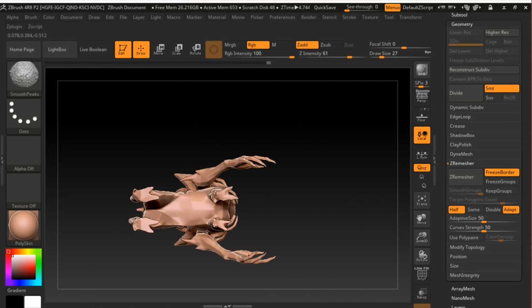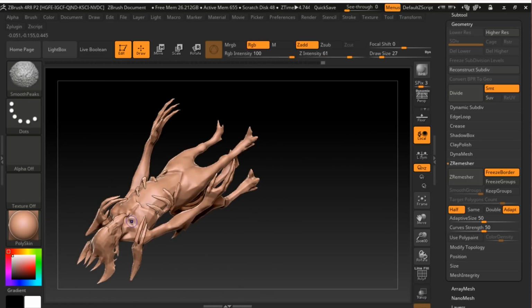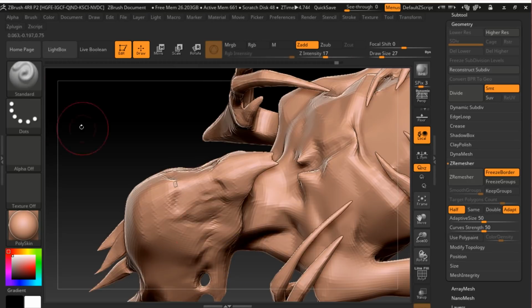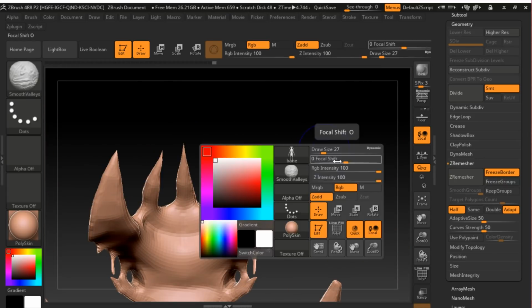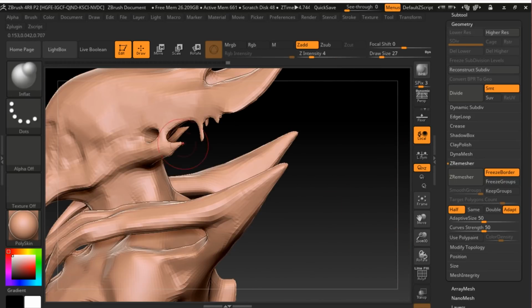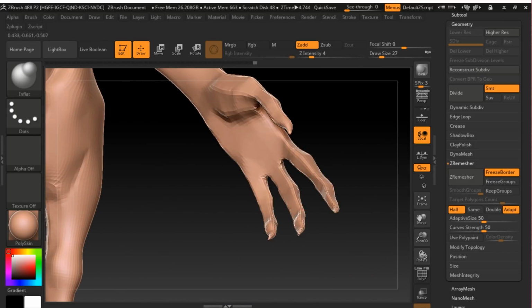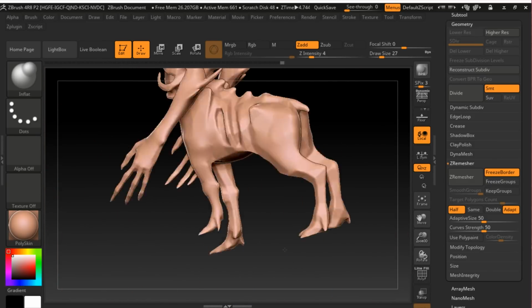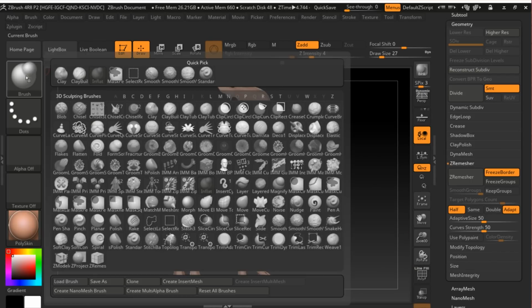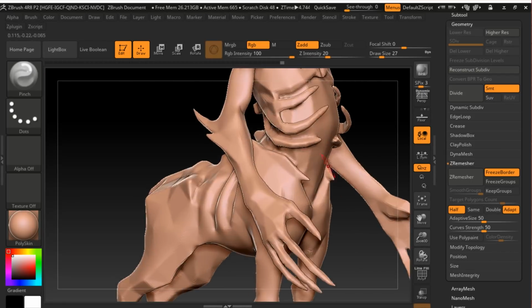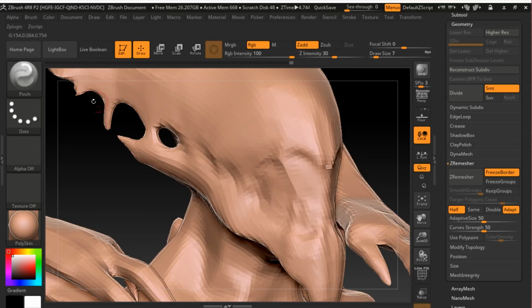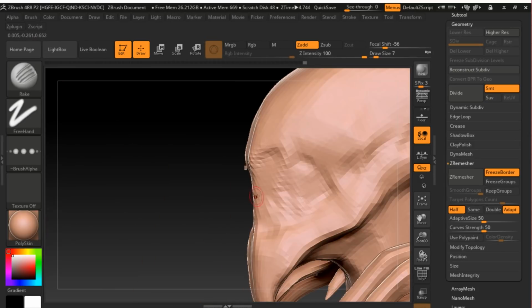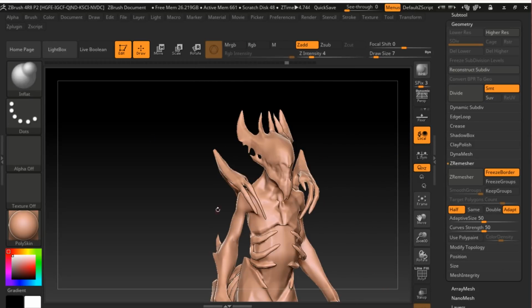It will be important to adjust your brush size for smoothing so as to avoid creating non-manifold intersections in tight areas. This part of the process is potentially time-consuming. Keep scale in mind while editing fine detail, since some of the very fine details won't be visible on the print. To add detail back in, you can experiment with different brush settings. Once smoothing is satisfactory, Z-remesh again to export with good manifold geometry.